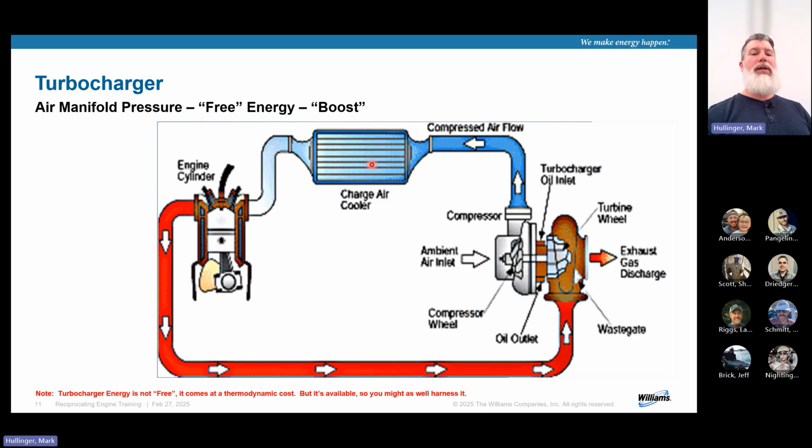And a lot of times since you compress air, it gets hot. So that's why we have intercoolers. And some of you have cooling water fans or scavenging air fans, I think, where it will actually cool. It's a cooler around the air, so that colder temperature goes into the combustion process and you get a better combustion. So some people call that boost.